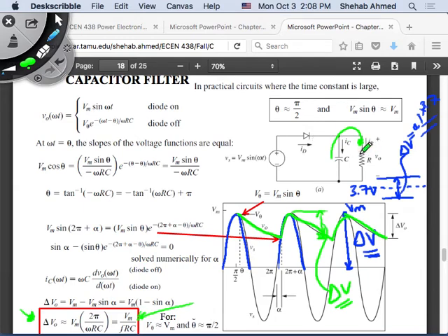If this resistor is large, meaning the current is small, then the value of voltage across the capacitor will not change much. If I'm not taking much current out of it, then its voltage will not change. Right? Capacitor voltage changes by drawing current out of it, or removing charge from the capacitor plates. That's exactly what's happening here. So that's one other thing.